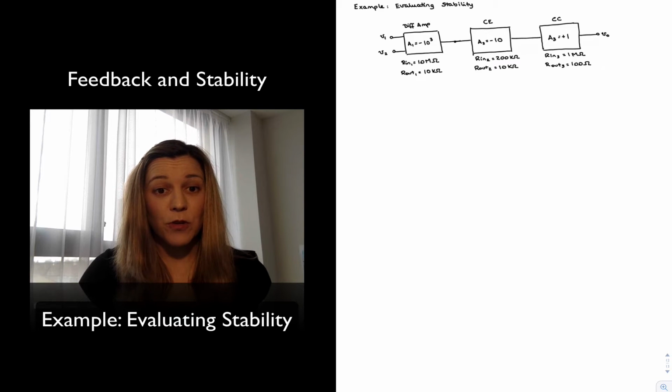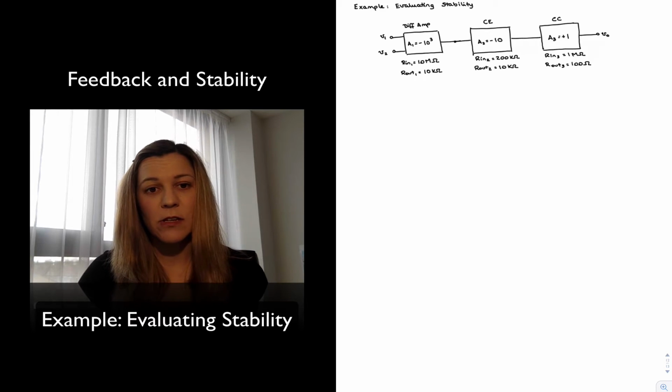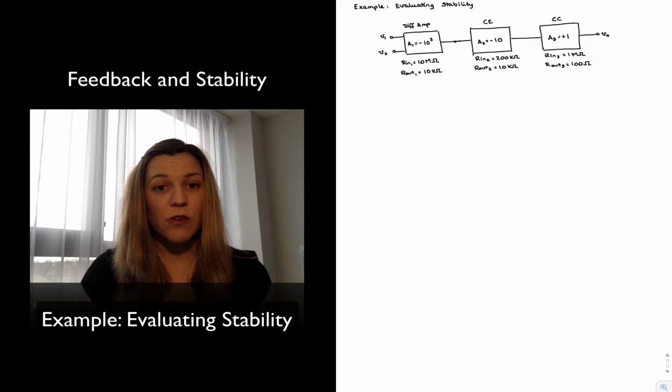Now we know that even though op-amps are typically DC coupled amplifiers, they're going to have a frequency response which doesn't have a low cutoff frequency, meaning they also amplify DC signals, but the frequency response will roll off at high frequencies due to the internal capacitances of the transistors, parasitic capacitances, and any load capacitances.